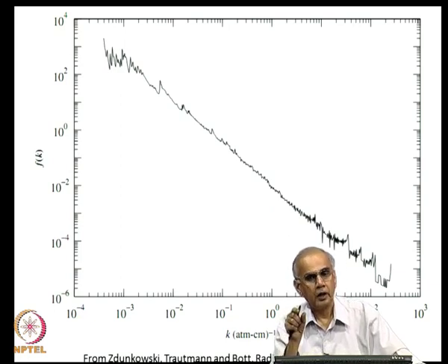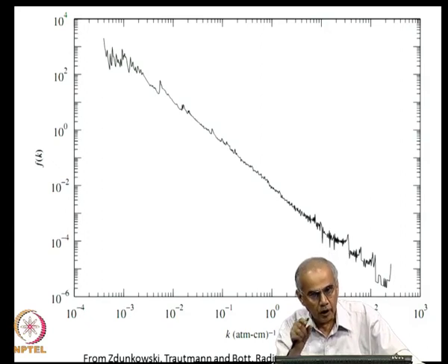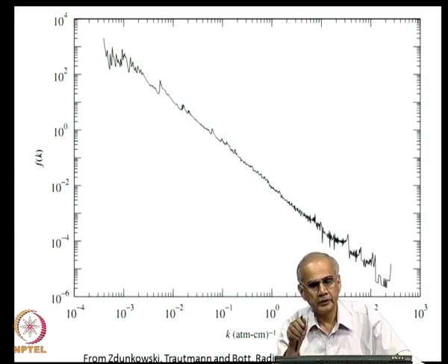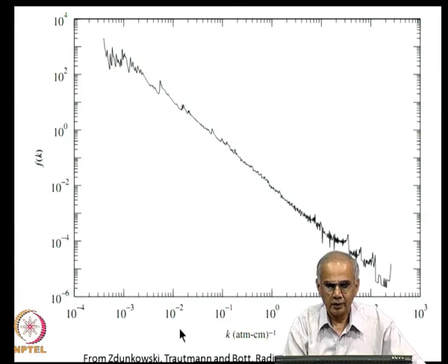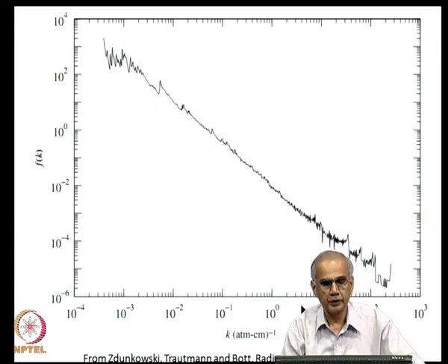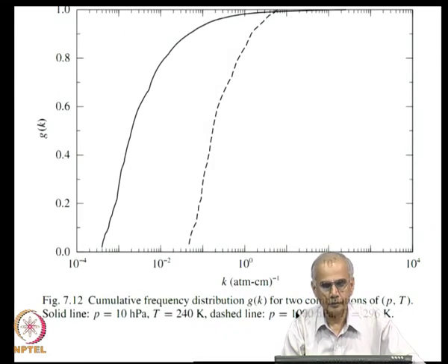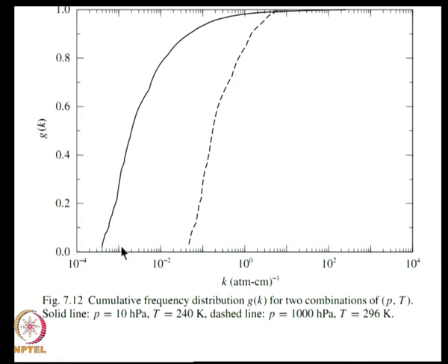So, if you take the black body function out of the integral, the remaining integration can be performed in the space of absorption coefficient, and even better in terms of the cumulative distribution. This is a very smooth function,